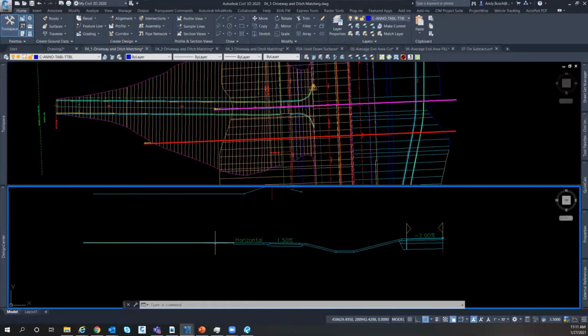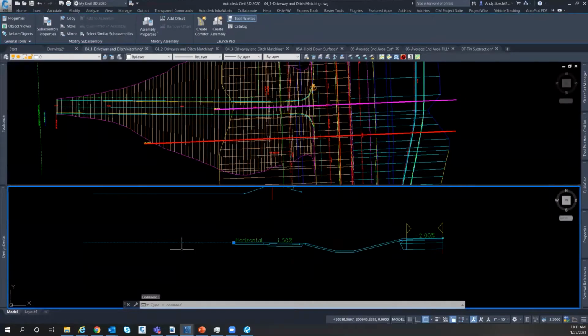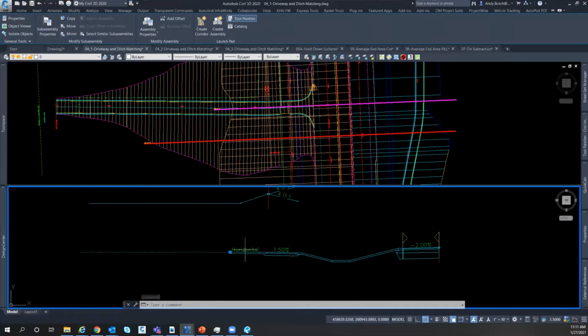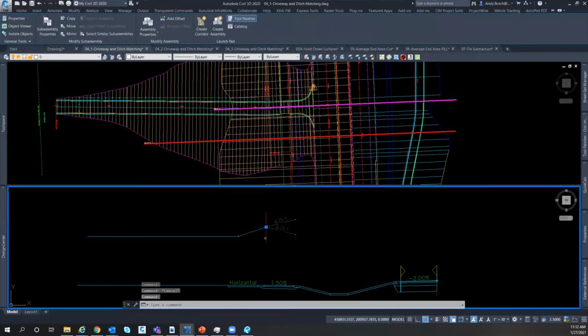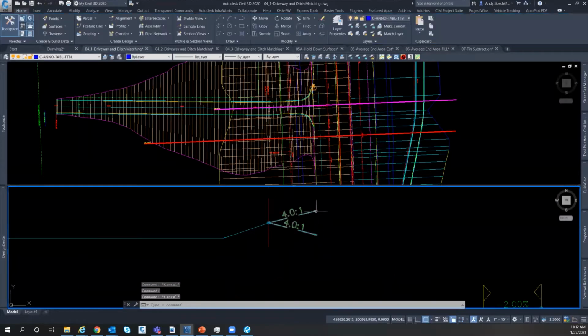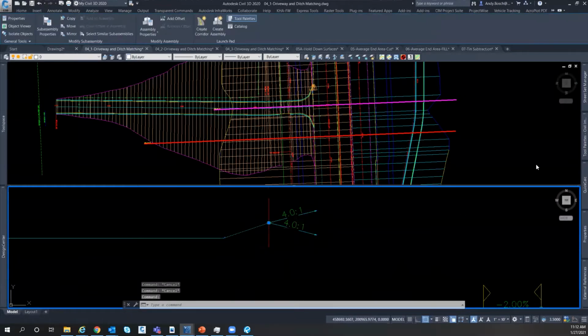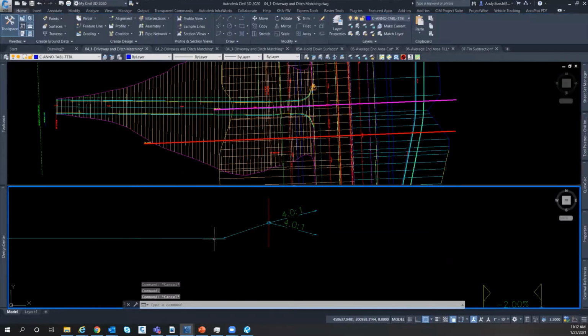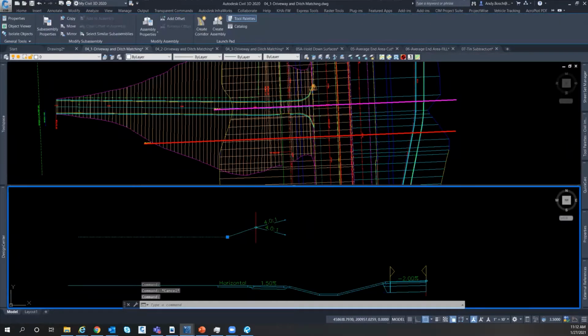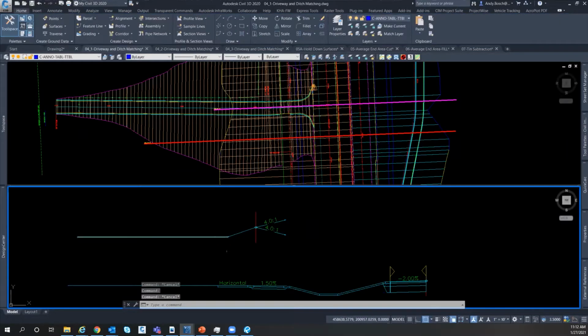So all I do is just add a generic link that goes out a given distance. One thing I'll note is that if you're not using one of my custom subassemblies, you can't really use this daylight generic one and attach on these edges, because this is just for display purposes. So I recommend, if you're going to do this, to utilize the generic slope to surface. And then you can attach another generic assembly off that and go out. So really you can move this portion down here and replace that, and you're going to get the same scenario happening.